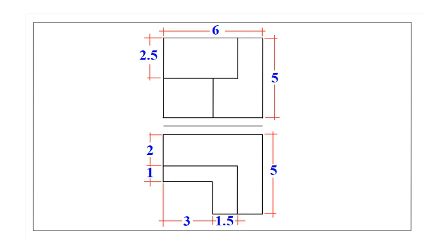This is the essence of a two-view drawing. The key is to always choose the two views that show the most characteristic contours and the most important dimensions. Alright, so you've decided your part needs the full three-view treatment. Now, how do you arrange those views on the page so it looks clean, professional, and easy to read?